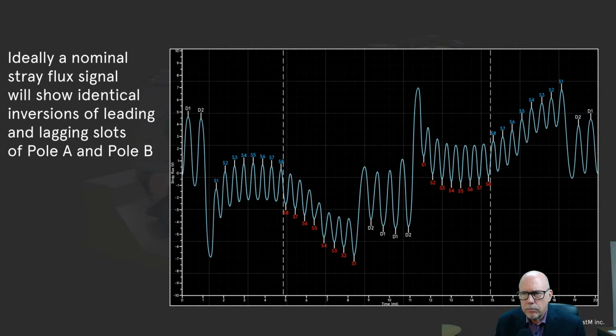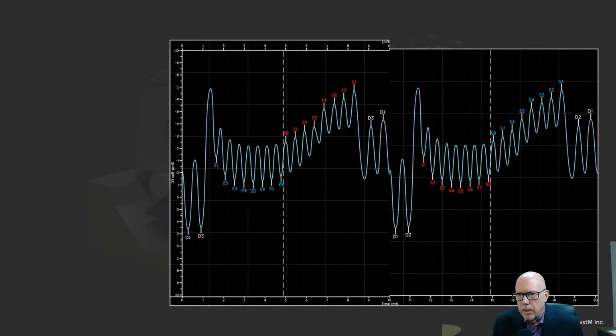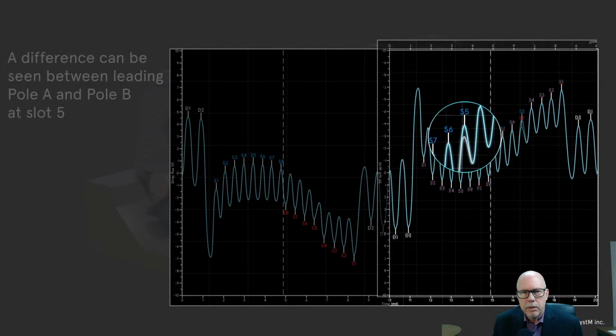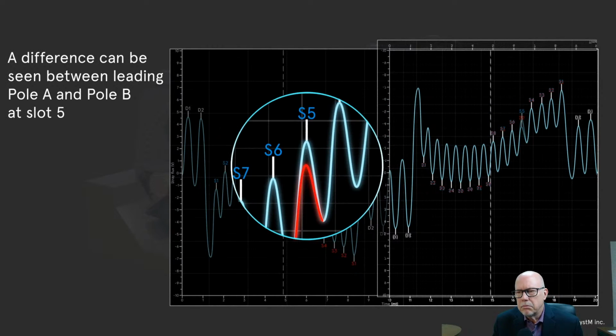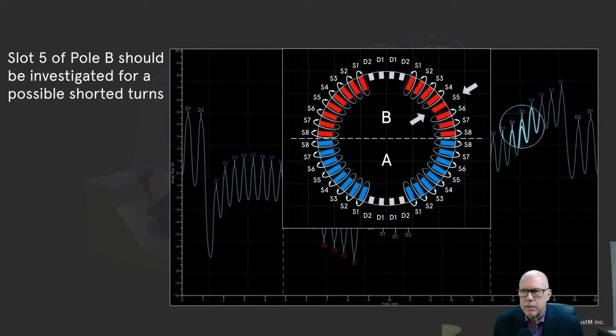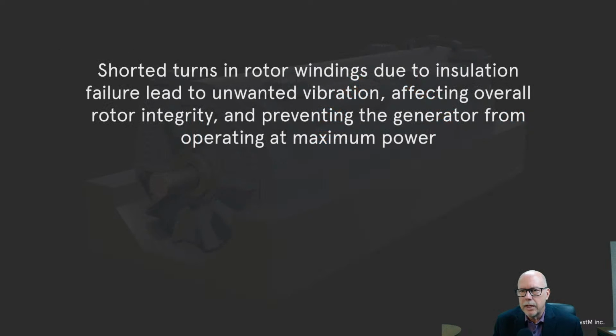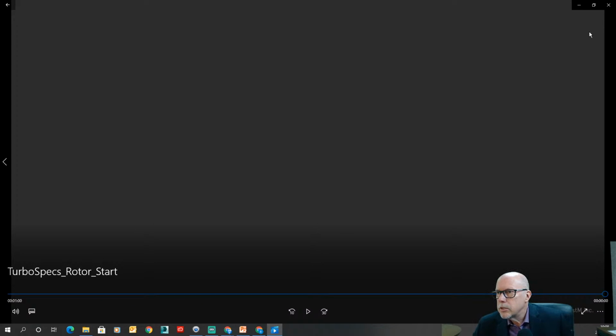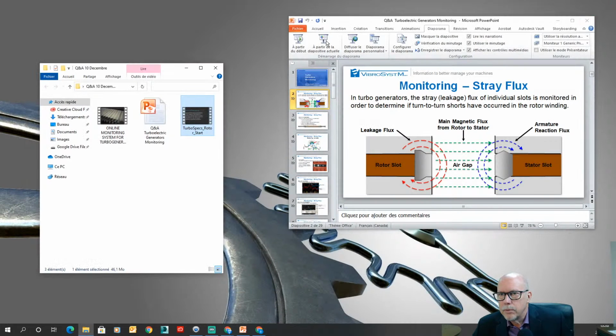And we are able to determine whether there are shorted turns by interpreting the amount of leakage flux of each coil. Okay, we have some pictures here of how this analysis is done, and we'll look at that in the presentation because there's no real flux intensity that's correct. It's a question of comparing flux coming from coils on different sides to be able to detect any issues with the shorted turns. Okay, so let's go back to the presentation.